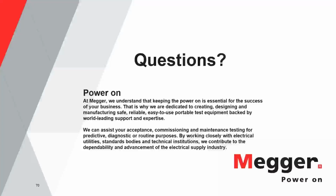Okay, so definitely the transformer has to be fully disconnected. Anything that is connected to the terminals of the transformer will be influencing the response you get from the test. So unless you have some big difficulties to do the disconnection, the best thing is to run the test disconnected. And if for any reason you have to run the test with the transformer connected, make notes and full documentation of that, so whoever runs a test knows and understands what he might be getting. So that will be for that question.